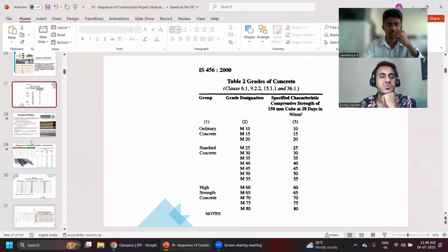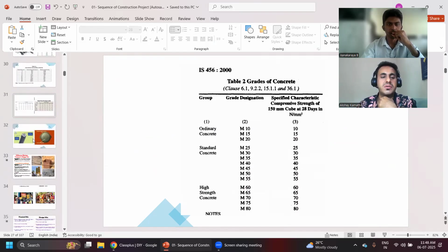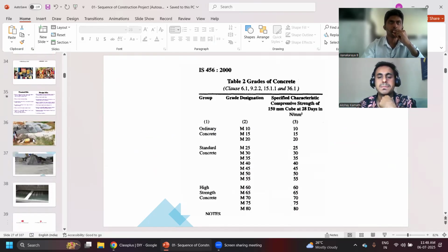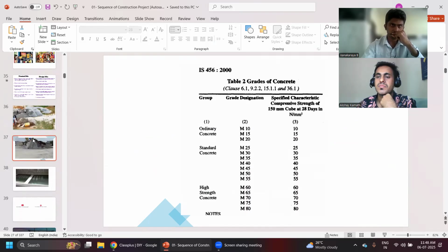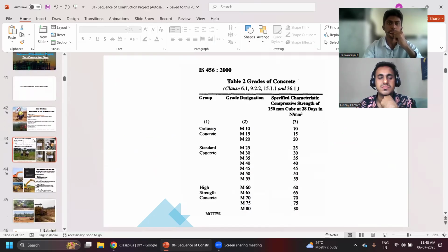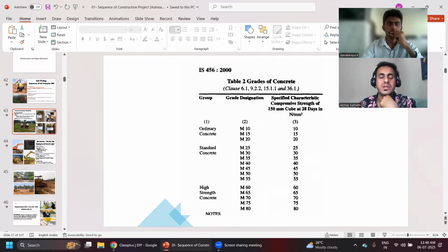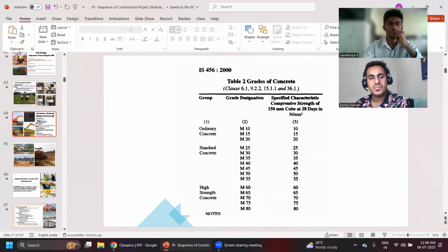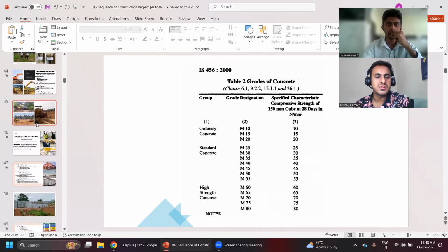Next question. What are the different diameters of the bar? Sir, currently in the market we have 8 mm bar, 10, 12, 16, 20, 25, and then up to 30, 32 bar. 32, 40 are also available. If we want something specific like 15 or 17, we have to order it specially, sir. Okay. Nice. Fine.